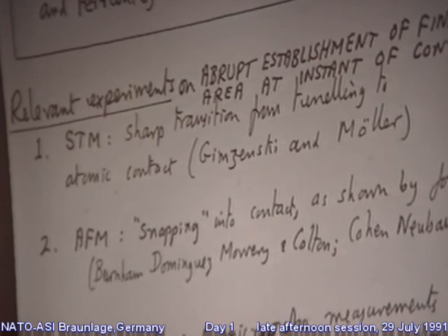And then there's the same adhesion-induced plastic deformation that I mentioned. Namely, if you touch two surfaces together, you have a certain amount of surface energy released, clearly, because you've got less surface area than you had when you started. And you can work out the conditions for this to be converted partly into plastic deformation. And that may help to give you this enlarged single crystal junction.